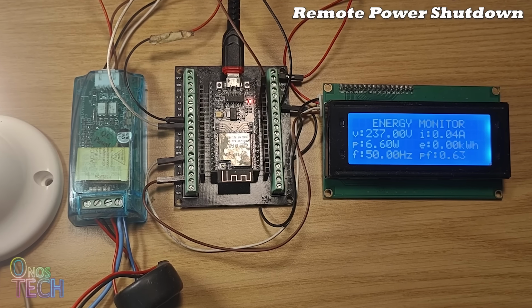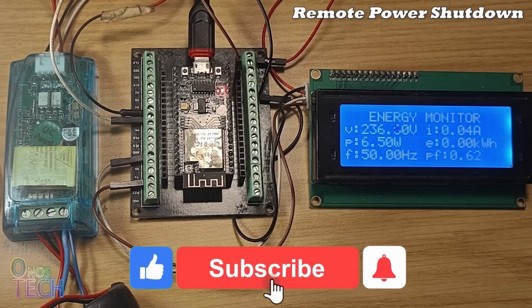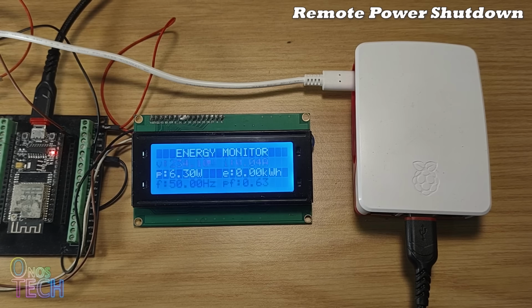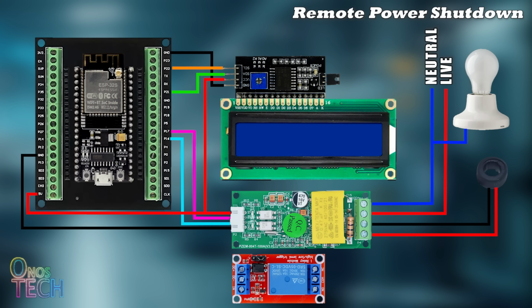In the last episode, we hooked up the ESP32 PLC to the PZEM-004T to monitor energy fluctuation and sent the data to the Raspberry Pi Node-RED Edge gateway. We will first upgrade the circuit from the last episode to include a relay connected to pin D4 of the ESP32 PLC and to the VCC and GND. The relay NO and COM outputs are connected along the live supply to the load for remote shutdown.